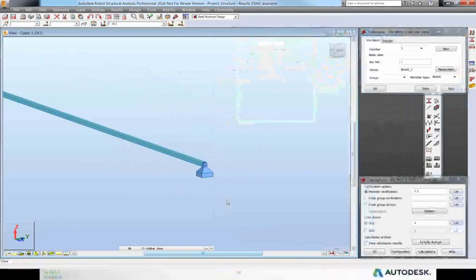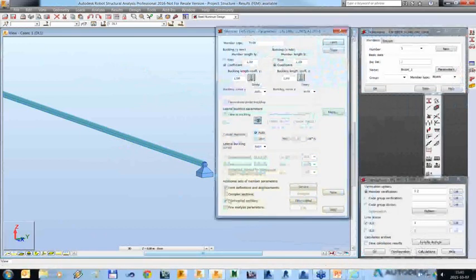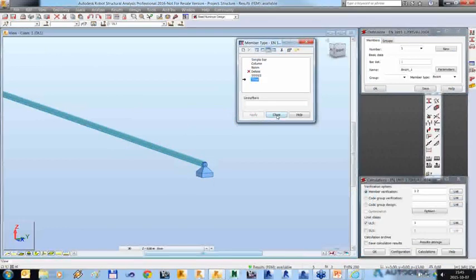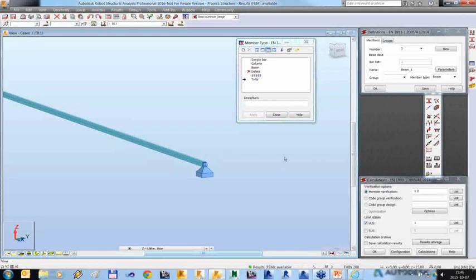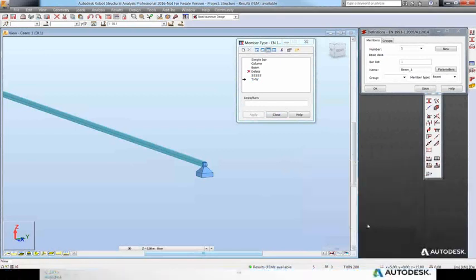So after activating the thin-walled section check, there are additional conditions. The correct section shape type must be set in the database, and the checkbox, I guess, at the end of the record must be marked. And then the rest of the design is made in the same way as for Solid's standard section database.